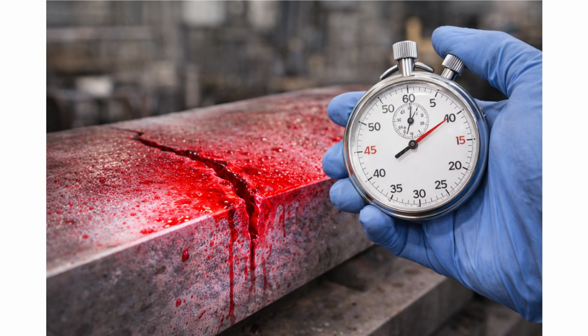It's crucial not to rush this step. If you remove the excess penetrant too soon, you won't get adequate penetration into defects, and you'll miss indications. However, you also don't want to wait too long, as the penetrant on the surface could dry out. Most standards and procedures specify exact dwell times that must be followed for that specific application.